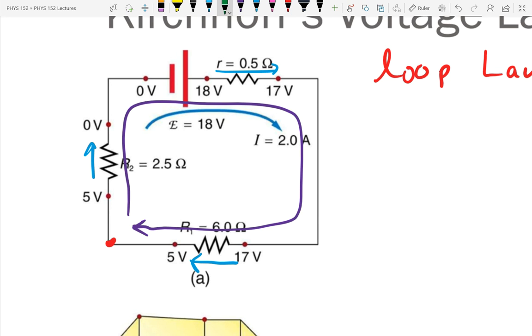That is, it's going to lower the voltage. So if the current comes in here and goes out here, it has to have lost energy, lost voltage. So the side where it goes out is going to be the negative side. The side where it came in is the positive side. So for each one, I indicate which side is positive and which side is negative. The negative is on the side where the current exits, where my arrowhead is. The positive is on the side where the current entered, where my tail of the arrow is.